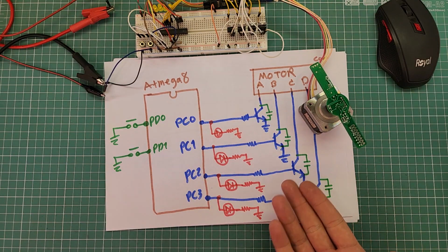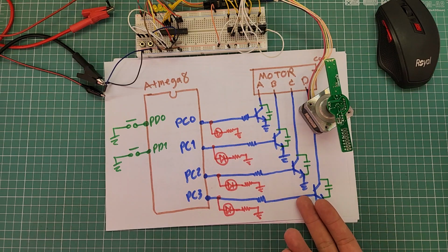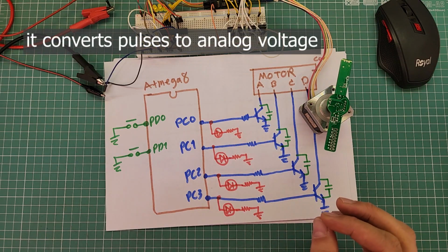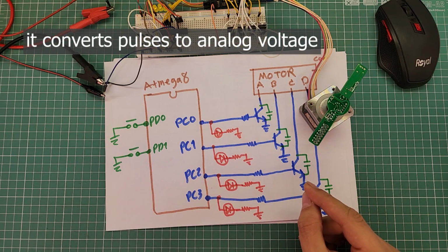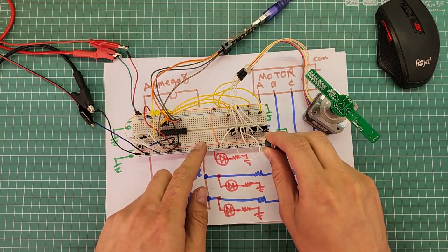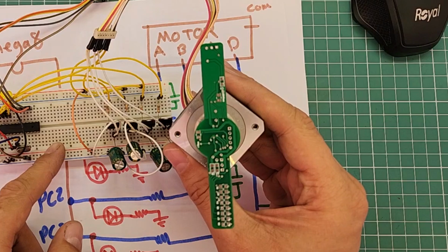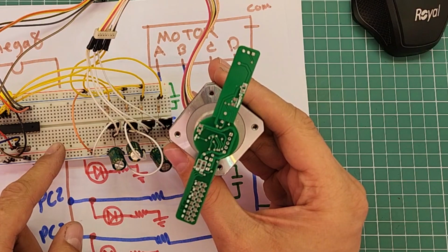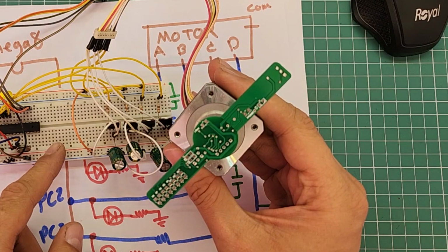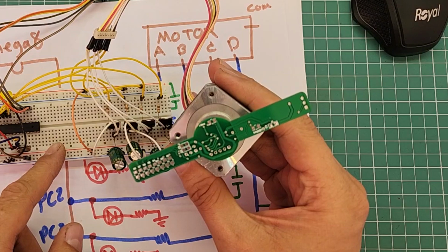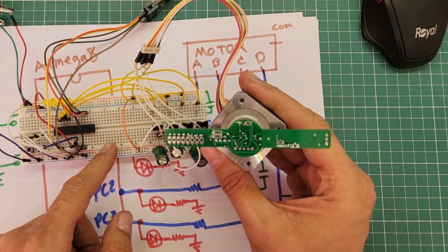Like this. Actually, these capacitors aggregate the PWM on-time voltage and form an analog voltage. Look at the shaft. The vibration and the noise is gone and the movement of the shaft is a bit softer, but still it is not what I expected. After applying microstepping, the movement of the shaft was not what I expected. This is the second problem that I mentioned earlier.